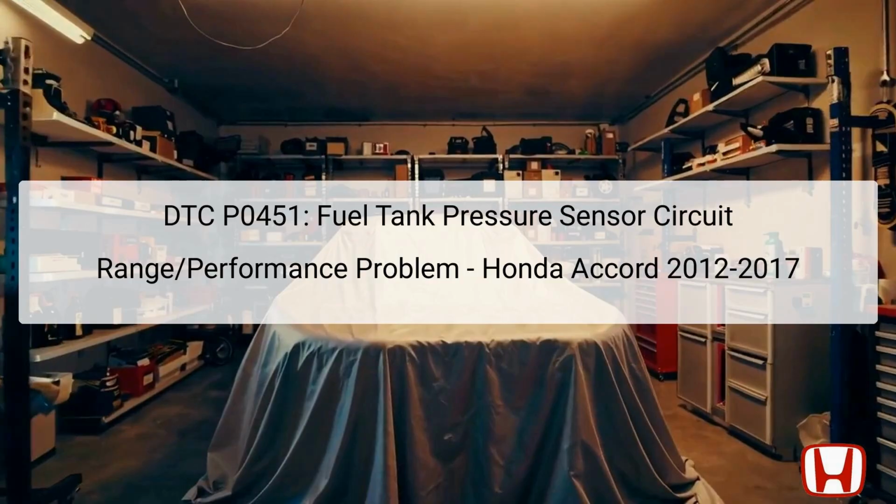The diagnostic trouble code DTC P0451 indicates a fuel tank pressure (FTP) sensor circuit range performance problem. This specific issue occurs in the Honda Accord models from 2012 to 2017 with the K24W1 engine. The FTP sensor plays a critical role in monitoring the vapor pressure in the fuel tank to detect any leaks in the evaporative emission (EVAP) system.